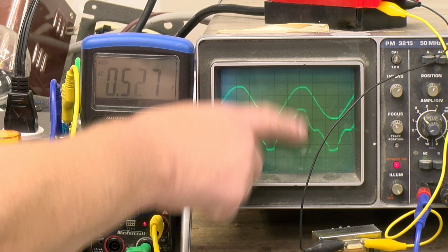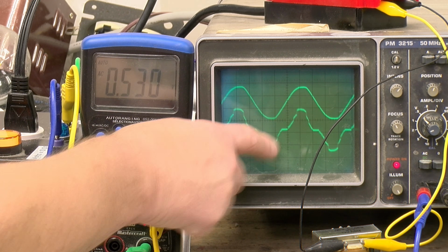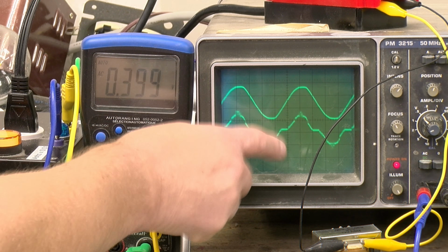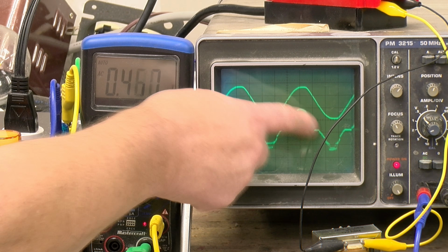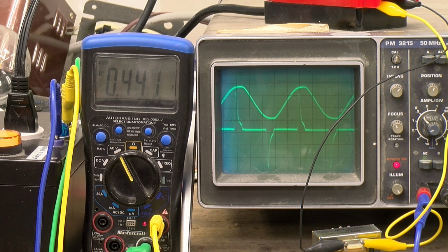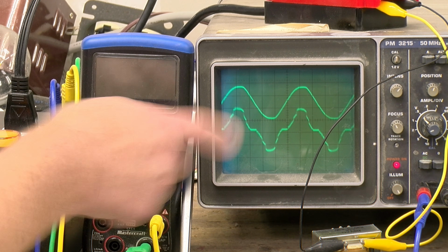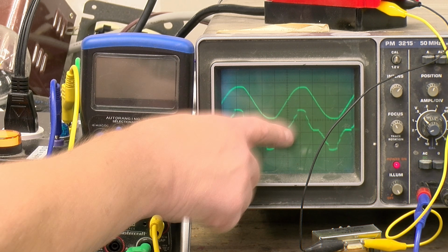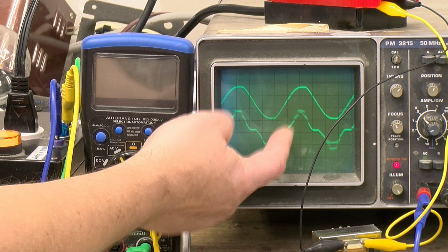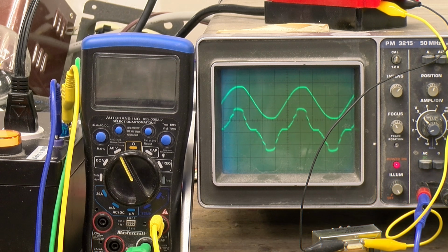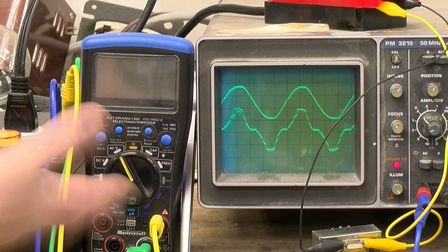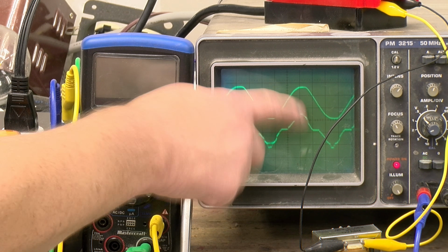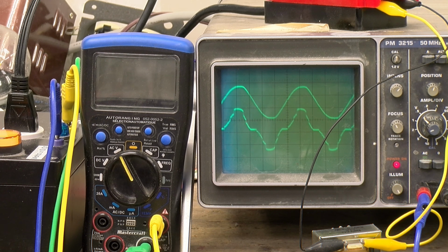And you can see they've, just like some of the better lamps, done a few things to try and make the current resemble a sine wave a bit better. And I guess as the thing occasionally uses less and less power, it goes back into that power saving mode. But when it's operating and it's drawing different amounts of power, you can see how the waveform changes a bit. And of course, that's the difficulty of a computer power supply, because it's having to adjust to the amount of power that the computer is using at different times.